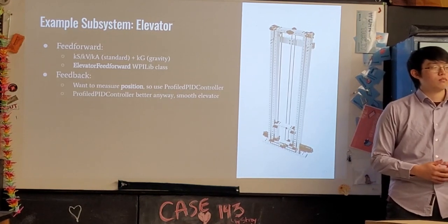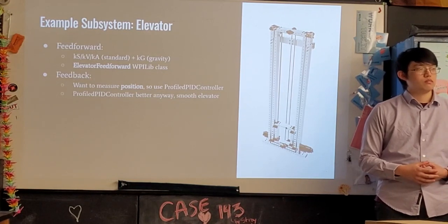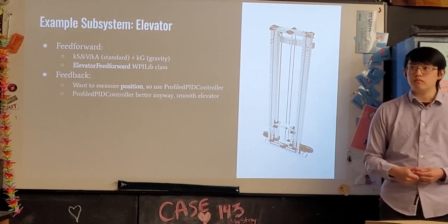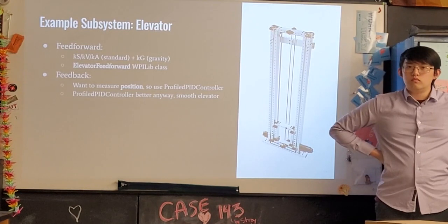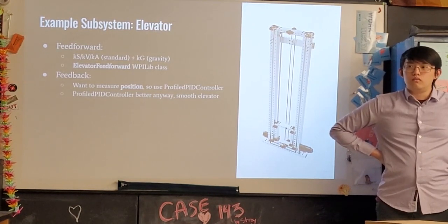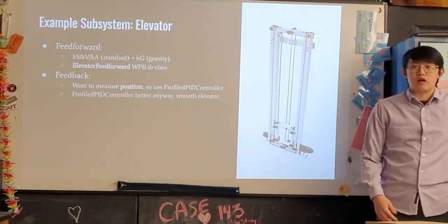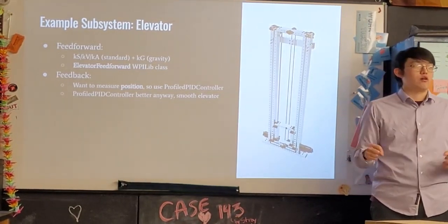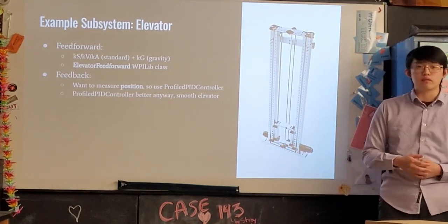So you're applying a voltage and then the motor is returning an encoder value after that. You take that encoder value, put it in your algorithm and adjust the voltage again. Exactly. But your question's really good: for feedback, you always have to have telemetry, some kind of encoder or measurement. It adds that complexity to your system. Again, a controller is basically a set of eyes on your motor, on your output, your plant. And in reality, those eyes are like an encoder, something keeping track of where your motor is, what your motor is doing.